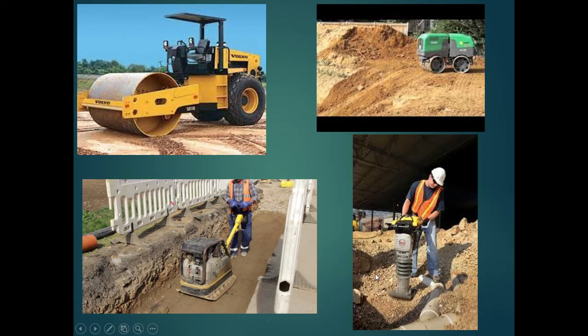So when you're watching these pieces of equipment as you're out there inspecting these projects, you're not just going to be sitting in a truck waiting to do your density tests. You want to watch them to make sure they're using this equipment correctly, and that they're not putting this jumping jack on top of the pipe or cracking the pipe, etc.